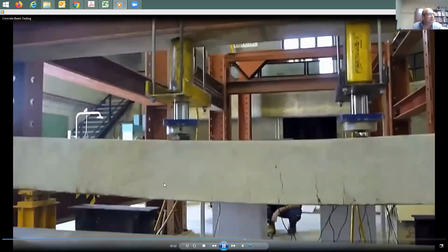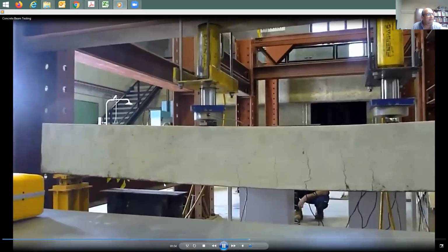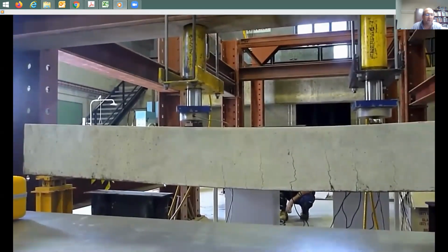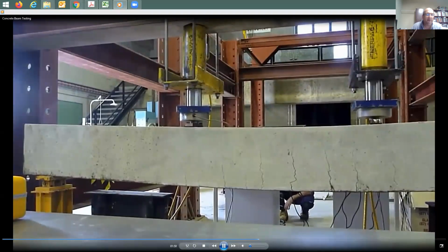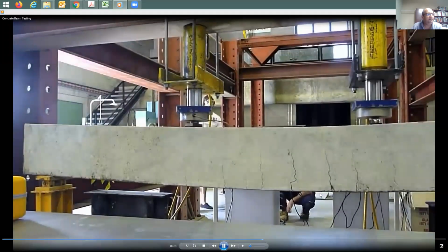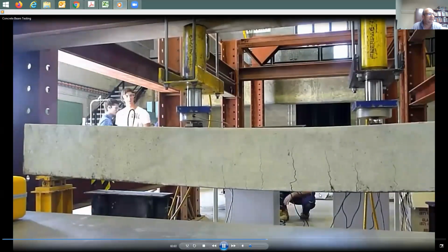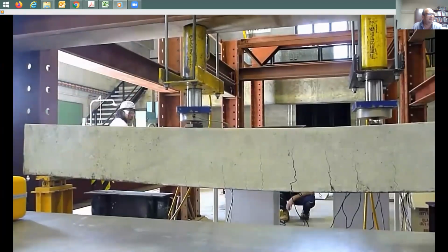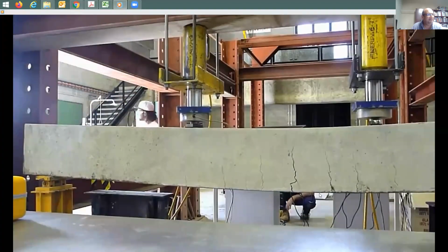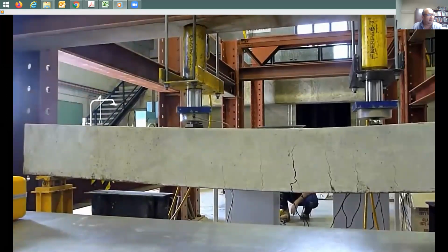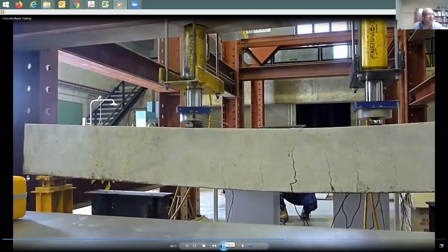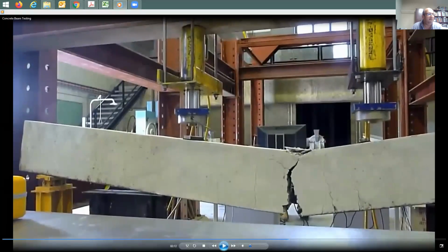Apply more load, watch for the cracks. Now the reinforcing is working, otherwise this beam would have been on the ground. Watching carefully, safety glasses. We're very close to failure here. Oops, now it failed. What happened to the rebars? They're gone. Snap. Just cut them off. The load was just too high.